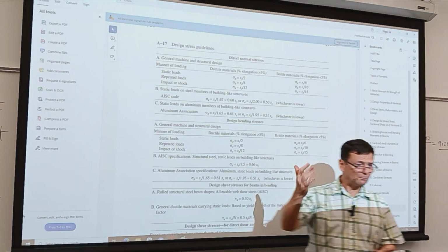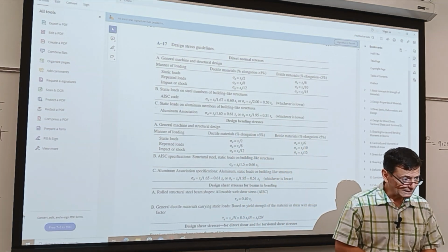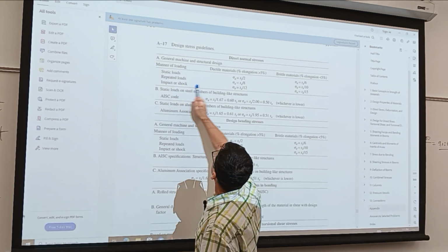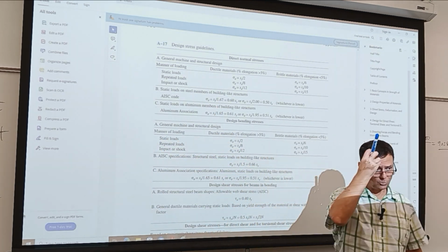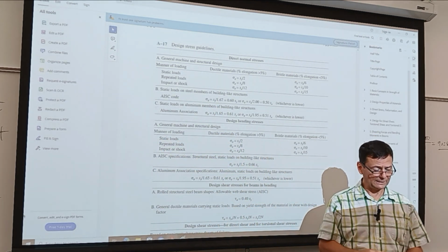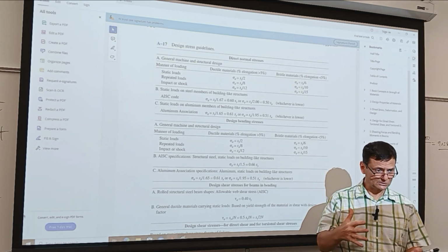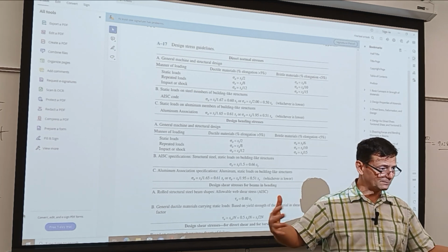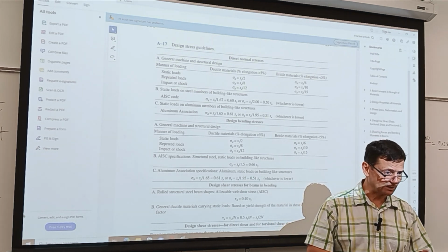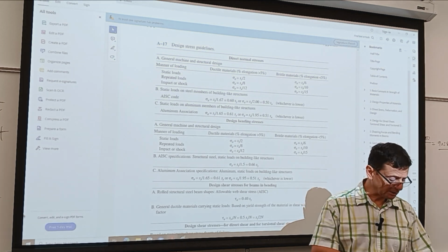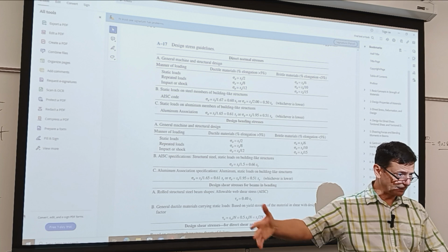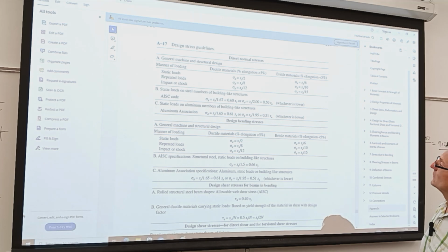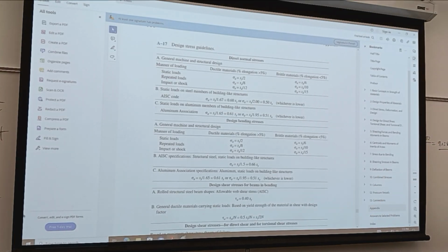I enumerated a number of reasons. The difficult one to capture is the repeated loading. And we have some knowledge for some of the materials like steel, aluminum, titanium, steel alloys. If you have repeated loading applied, steel has the property that at a certain stress level it can last forever. Aluminum builds up fatigue even at low stress level. So that's why aluminum is known not to have an infinite fatigue life. So aluminum frames, for classical frames of aircraft, have a limited life as a rule. Anyway, so 1 and 12.